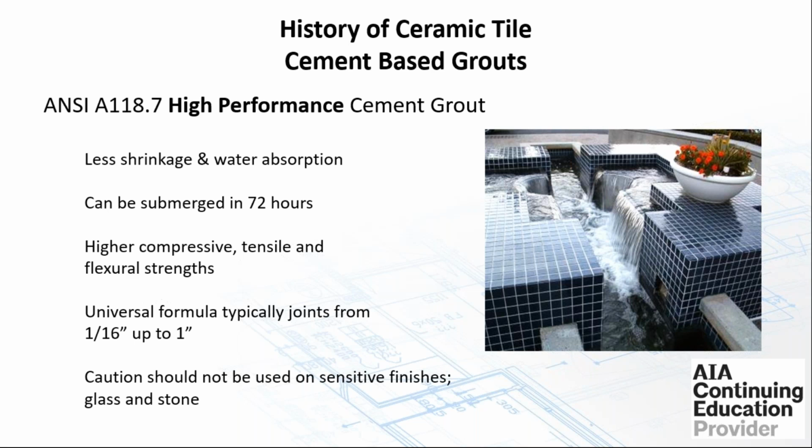It's just one product, and the aggregate we're using with this product will allow you to go from that tight joint all the way up to a 1-inch wide grout joint. Again, if you have a sensitive finish, glass, certain stones, metal tile, test it first before you start smearing the whole area and then find out you're scratching the surface.